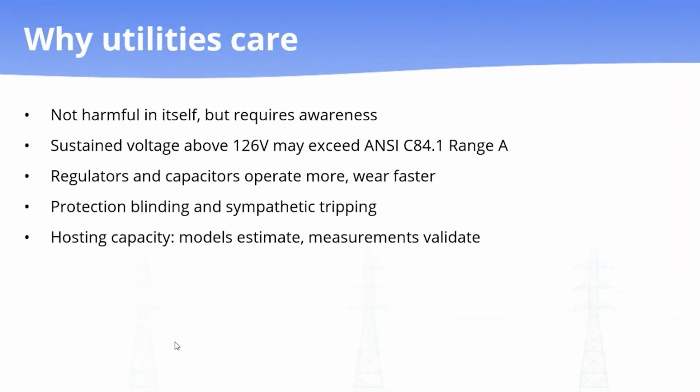That shows up as more operations, extra tap changes, capacitor switching, sometimes hunting. It's mechanical wear on equipment with a finite number of operations, so you pay in shortened life and maintenance rather than outages, which is why it often goes unnoticed.